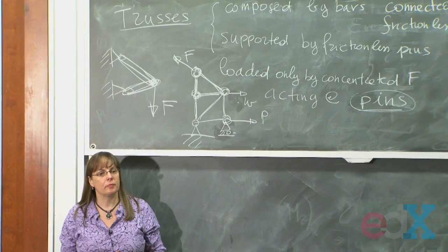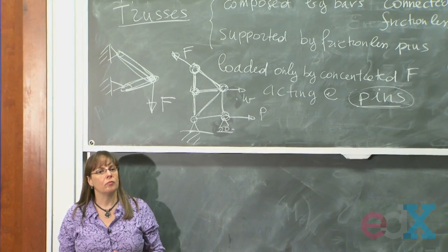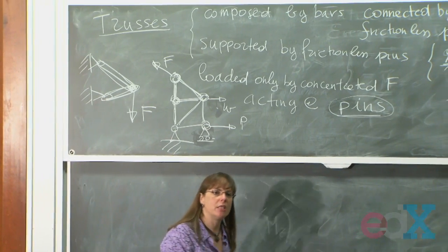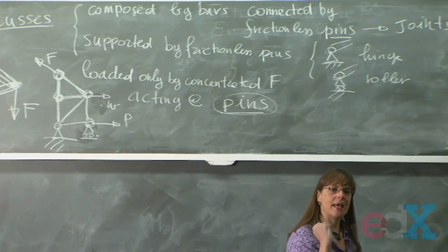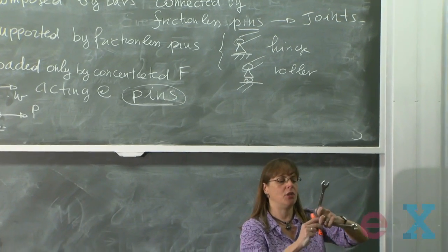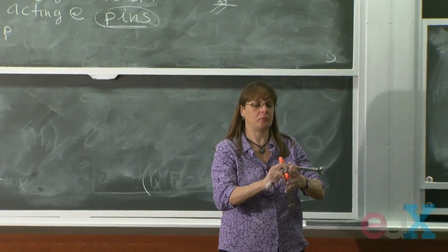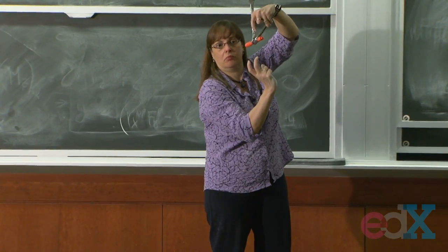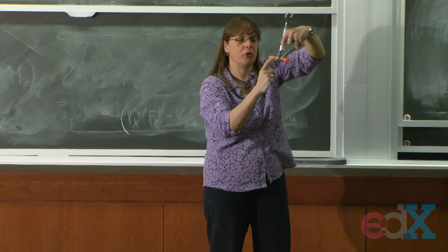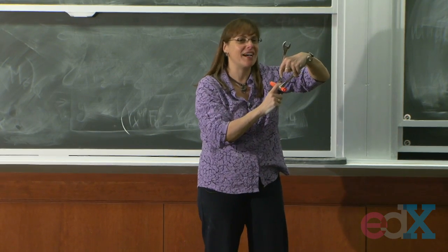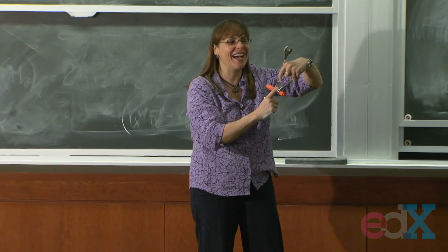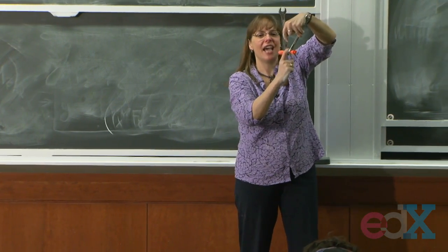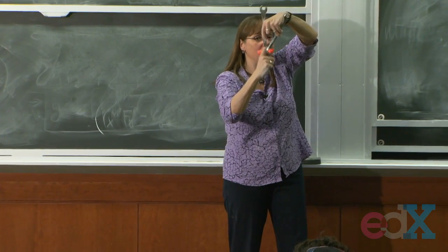When you say apply, do you mean like we can only think about the forces at that point? Yes, you have to imagine that all the forces that load the structure are applied at that hinge. You have to imagine that somebody comes in, and this is the hinge, and hangs a basket of rocks from here. Notice not wood. I was going to say a basket of bananas, but I caught myself at the last moment. Okay, so he hangs a basket of rocks right from this pin.